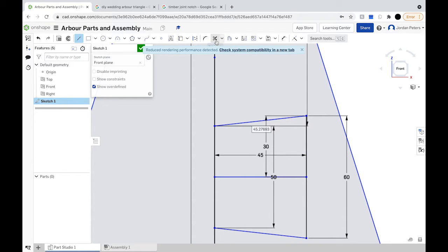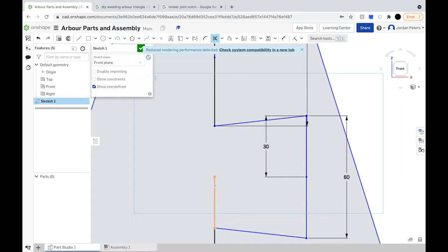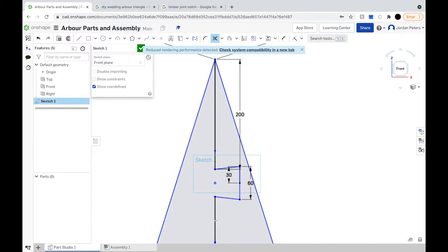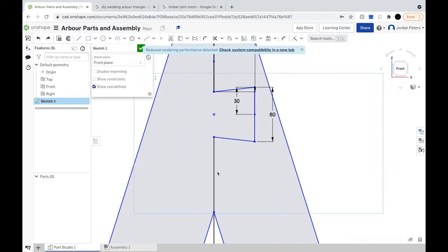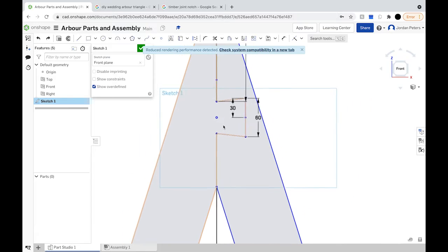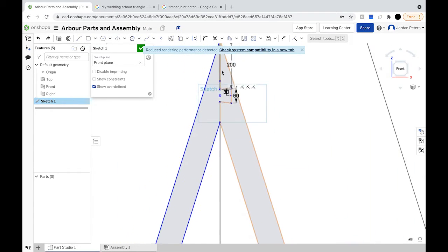So we're going to use our scissor tool up here. You may need to left click and grab it. And we're going to delete this center line, that's unnecessary. And delete this line and this line multiple times because there's a few of them in there. We're going to go through and delete as many as we need of this line. So I'm just going to keep clicking until they're all gone. And then once they're all gone, just press Ctrl Z to bring back one line. That's just a nice little trick, save you a bit of time.